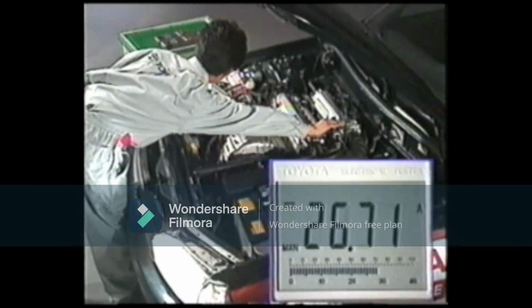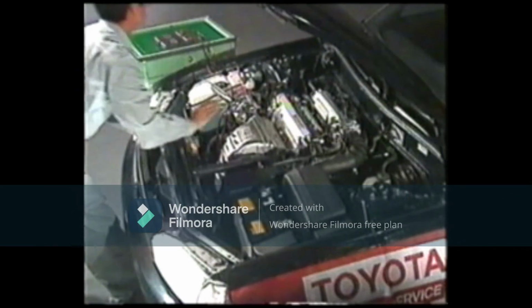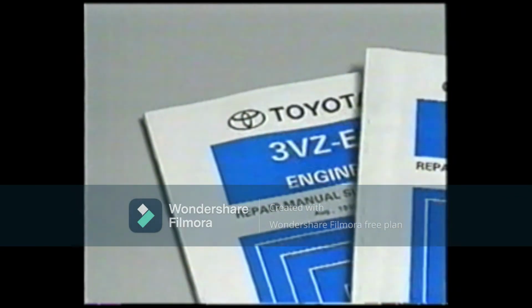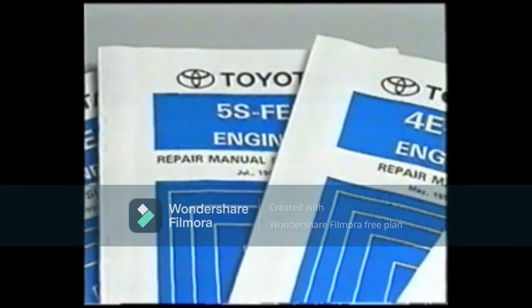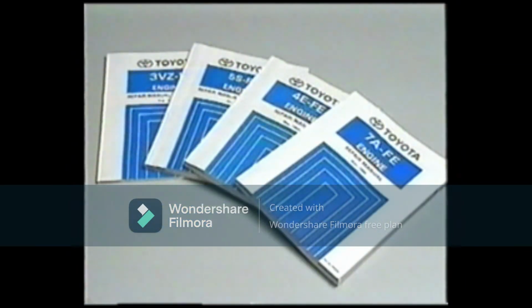If all voltage generated by the alternator is within standard, you can make your final determination of the charging system condition by doing a with-load test. In the with-load test, if the amperage generated by the alternator is at standard or below, you can assume that the alternator is at fault and inspect or repair it as necessary. You can refer to the repair manual for the relevant engine details, how to carry out a test with and without load, and how to determine whether the charging system is otherwise normal or not.